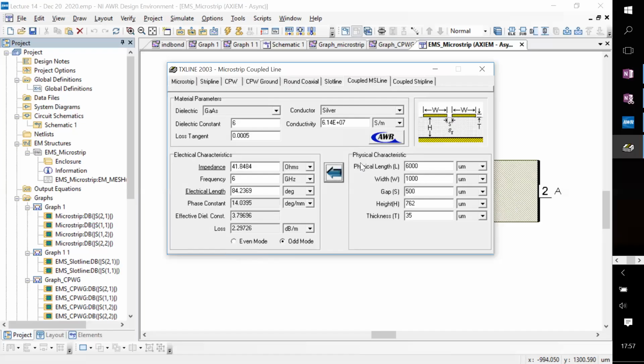And this actually, as I think I said many times before, is connected to this fact that the microstrip is sort of a quasi-TEM line, and this also affects the properties of some devices if one makes coupled microstrip lines instead of coupled strip lines. So in the coupled strip line, this problem will not happen. Even and odd mode impedances will be the same. Even and odd mode phase constants will be the same. So we can just check that.